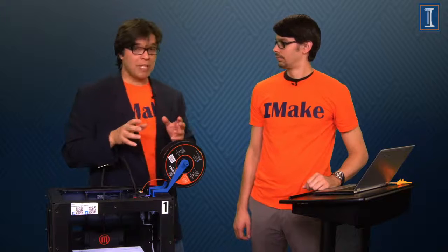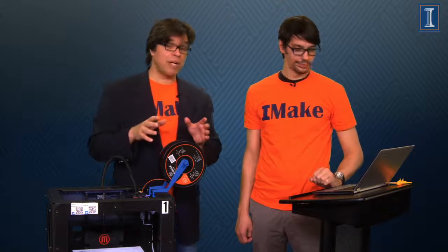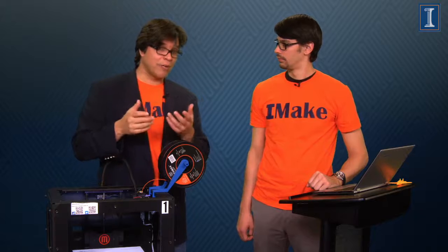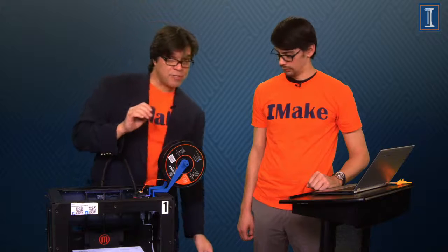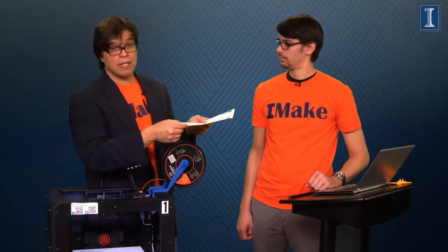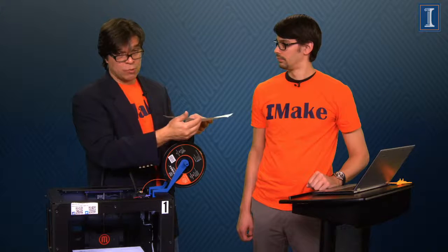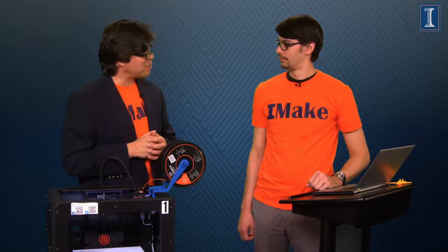Typically in the Maker Lab, we print most of our objects at a layer height of around 250 microns. What that means is that 4 layers equals 1 millimeter, or in other words, each layer is only a quarter of a millimeter thick. As a point of reference, the width of a sheet of paper is about 100 microns. The Ultimaker, as well as the MakerBot, will print something as fine as the width of a sheet of paper. But typically we don't do that, because the products that we use look pretty good at 250 microns, and we don't want to stick around for days to have the object print.